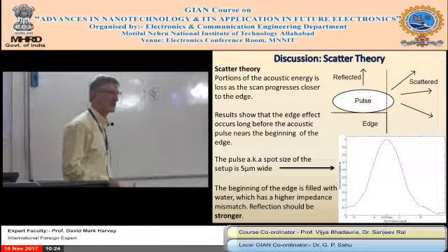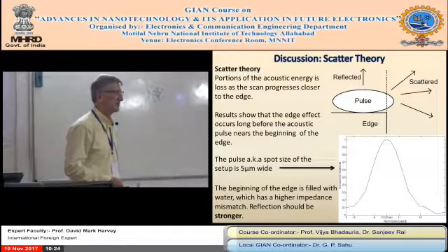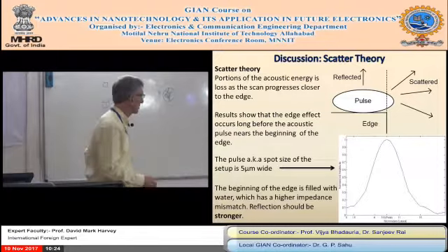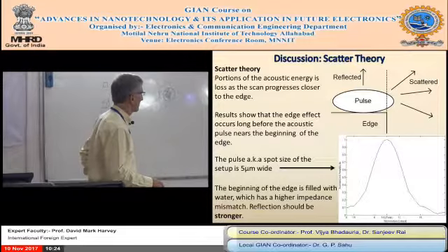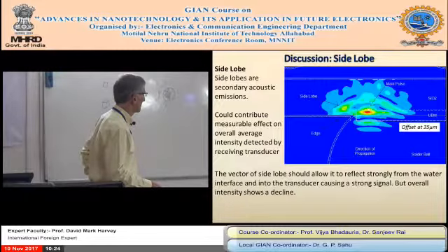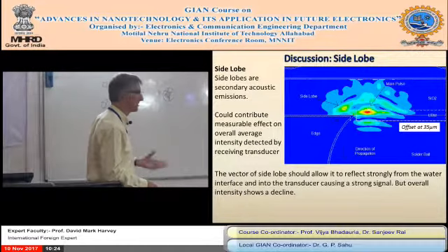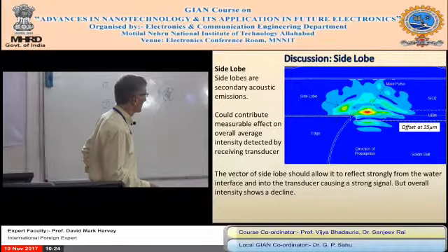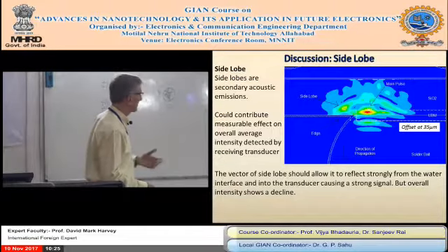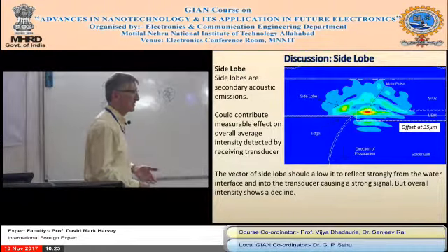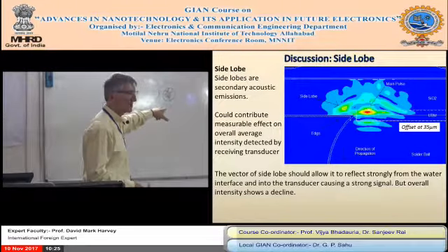Here's some pictures. After 2 years and maybe a bit more, hard work and answers, you might get some simulation results. So there's just one. I've got a whole load of these. The ultrasound pulse comes from the top there. Red is high intensity, and it goes down, that's the peak, going down to the light blue, which is the lower intensity. So most of the signal's there, but you've got a side lobe there and a side lobe there. And there's a solder joint edge. You expect that side lobe to continue down into there. On the simulation, it seems to stop around about there. So if it stops, it means no energy is being reflected back. So you're going to have this dark ring, which is what happens in reality.